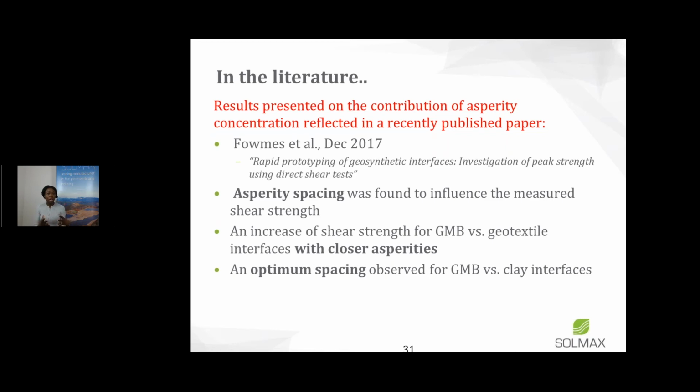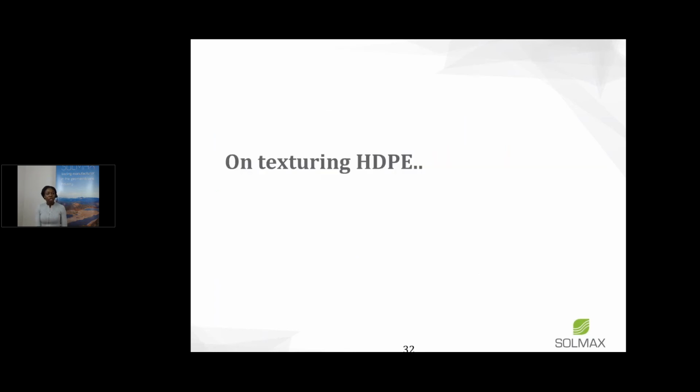So this corroborates what I already shared from our testing so far. Another interesting thing they found was that there seemed to be an optimum spacing between geomembranes and clay interfaces. We haven't tested on clay, but that's one of the next steps that we're going to look at, to look into this a little bit more.